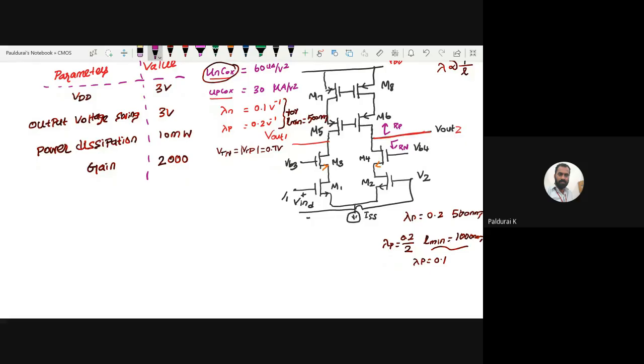So here obviously you want to give biasing voltage, right? VB, this is another biasing voltage. Let me call in general this V1, VB1, this is my VB2, this is VB3, this is VB4. So 4 biasing voltages, right? It must be connected to either ground or negative power supply. So far any doubt?